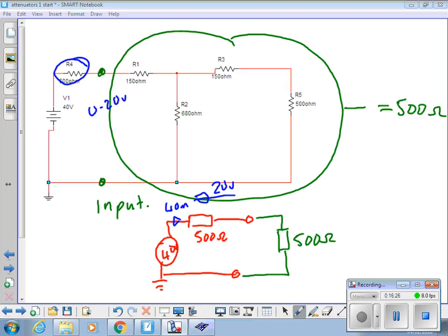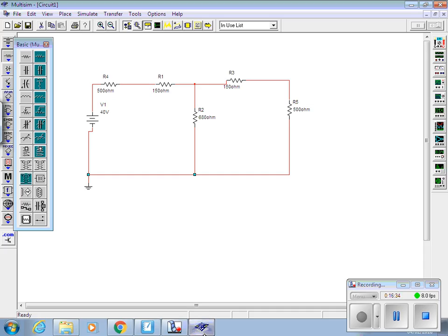Yes, alright. It's a little bit of a difficult concept to get, but once you've got there, so in Multisim, what we need to do, and I'll save this and we'll pick it up next week because we're just about finished, is put a voltmeter across there to measure the output voltage.